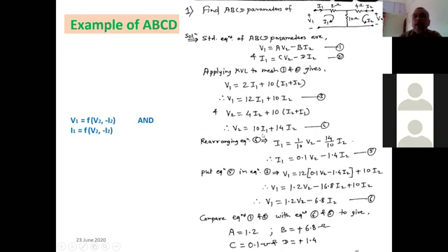So take I1 on one side and the other terms on the other side. So this 14 I2 you take on this side. So V2 minus 14 I2 will be on the other side, and divide by 10 so that it will be I1 only. So rearranging equation 4, I1 will be equal to 1 upon 10 into V2 minus 14 by 10 into I2. That is, I1 is equal to 0.1 V2 minus 1.4 I2. So let us say this is equation number 5. So we got the second equation, which is of the standard form of ABCD parameters. So we will be able to find the values of C and D from this equation. Okay, that is equation number 5.